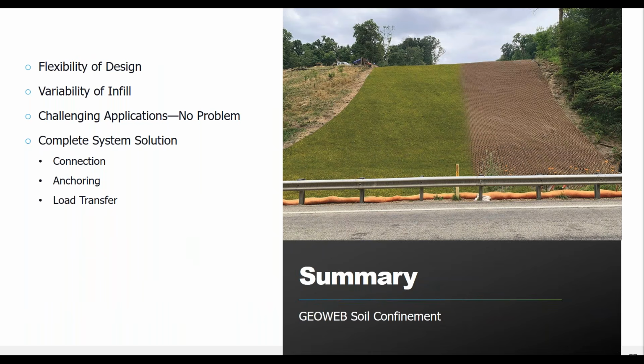Okay, so we've reached the end. Summary: the GEOWEB Channel Protection System has great flexibility of design. You can have a variety of infills to meet your specific project needs. We can fill with topsoil to get vegetation, nice green grass growth. You can use crushed aggregate if you're in an area where grass is not appropriate or if you're fully underwater. And you can use concrete to help protect against high velocities or if you have turbulent flow.